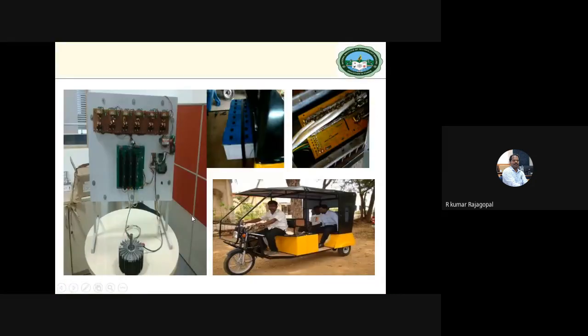So the final device we verified with the 2-wheeler, 3-wheeler, that is auto type, and trucks also. See, this type of motors will be different capacity-wise, maybe for two-wheeler, three-wheeler, only that changes. Battery is also the same. See, this battery is basically 48 volt each slot. This is blue 1, 2, 3, 4, 12 volt into 4. 48 volt will be required. But see the IC, only the algorithm, hardware, everything is the same. Driver IC will be different for two-wheeler, three-wheeler and trucks also.